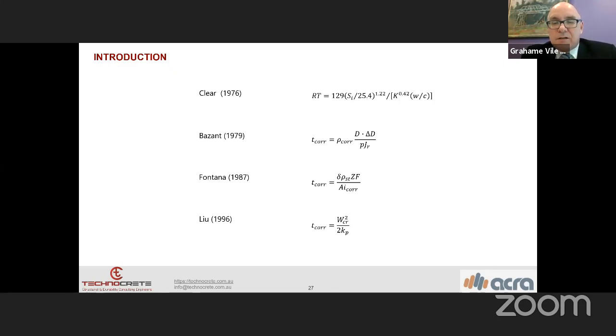Has there been research in Australia about bolting carbon fibre to concrete, or is it always adhered? What other alternate anchoring methods are there? For strengthening? Yes, for carbon fibre strengthening. Okay, we have 3 products for carbon fiber strengthening. We have wrapping, which is fabric, like flexible CFRP, and it can be wrapped around the structure element. We have carbon fiber laminate, which is not flexible, and laminate is more suitable than wrap for shear strengthening. If it's for shear strengthening, we use carbon fiber laminate.